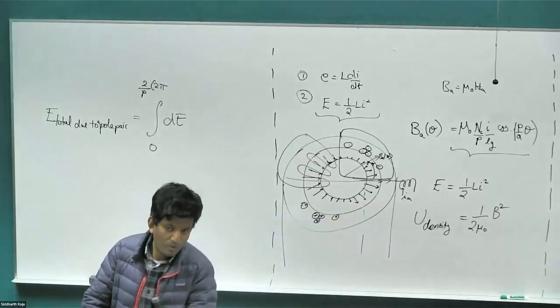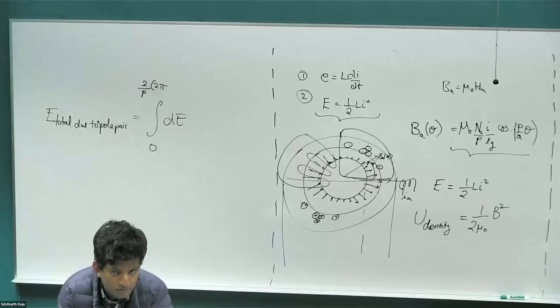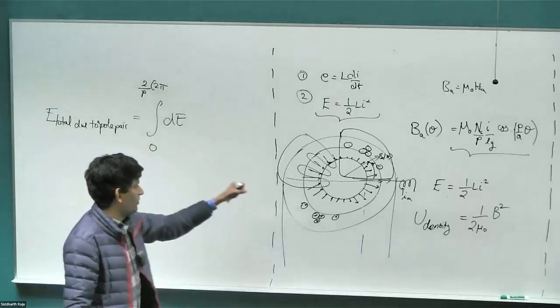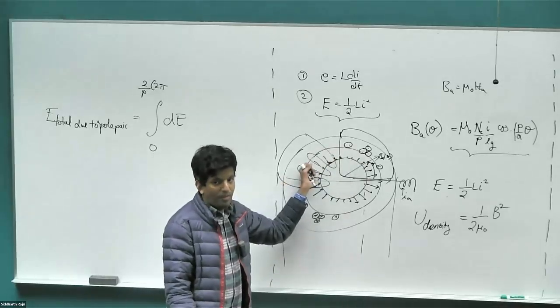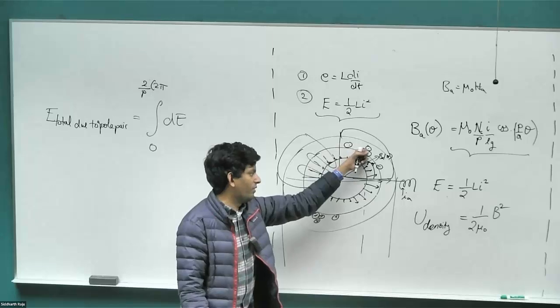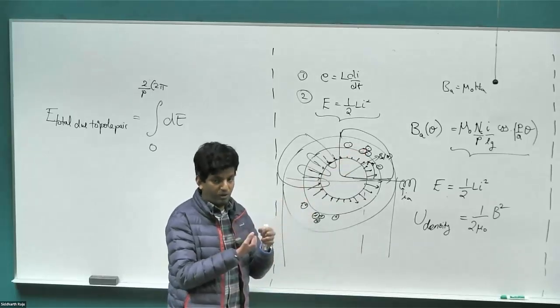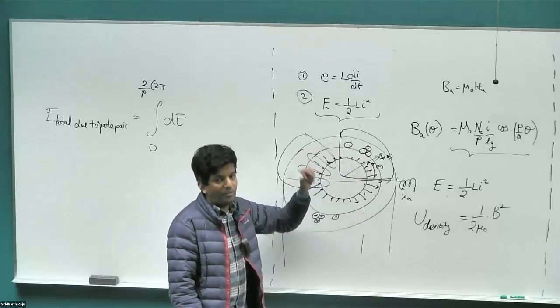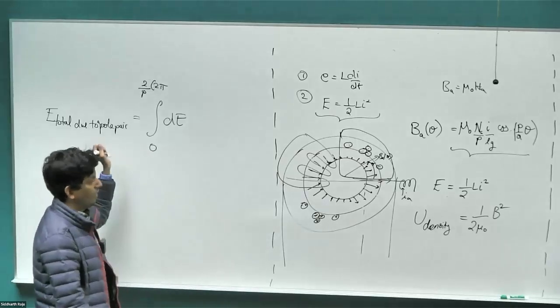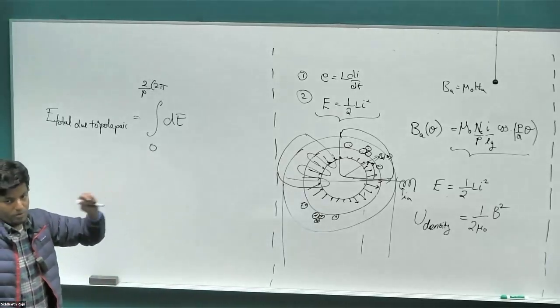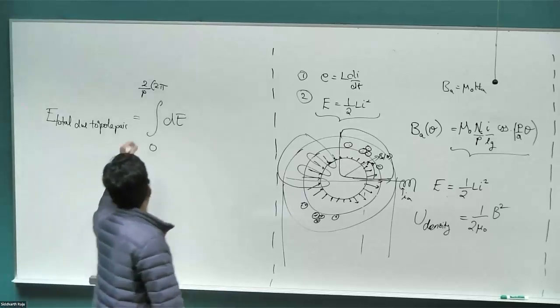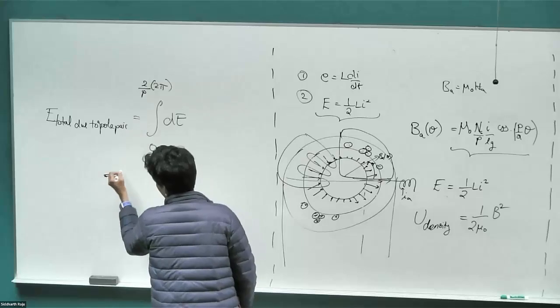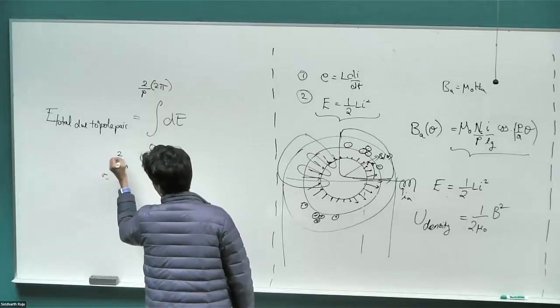Yep, Jonah. So that model we had before, is that representing the entire motor? Is it just one set of poles? Which model, the circuit model that you drew before? No, that's for the full motor. Okay. So whatever I'm deriving is the energy of this half, let's say in a four-pole case, this half alone. But then what happens with the inductance will depend on how I connect this winding with this winding. There are multiple ways of connecting them. For now, just hang on. We are deriving just the energy of one set of coils alone, and then we'll see how it interacts with the other set of coils. But the circuit diagram that I drew is a per phase equivalent motor model for the full motor.